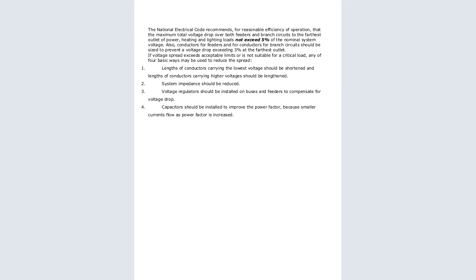Why do we need this? It is because we need to lower the voltage drop. The more we lower the voltage drop, the more the efficiency and the working of the cable. When it exceeds 30 meters, the best option is normally to add a pole so that the cable can be shortened. That is a basic way of shortening the cable.